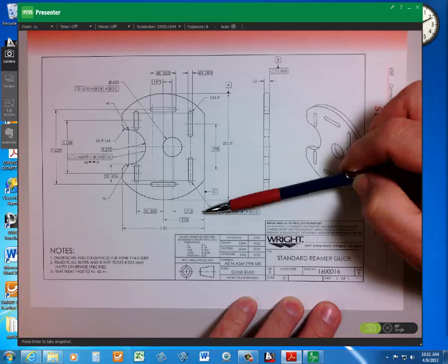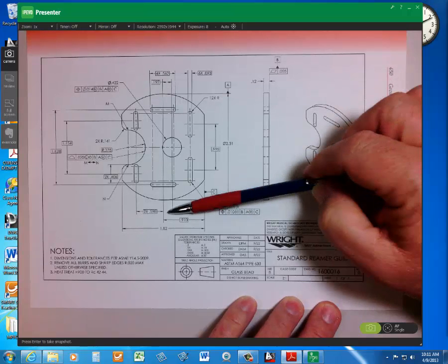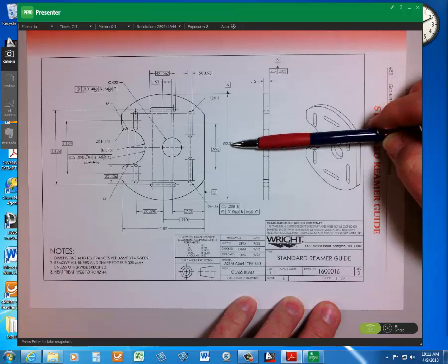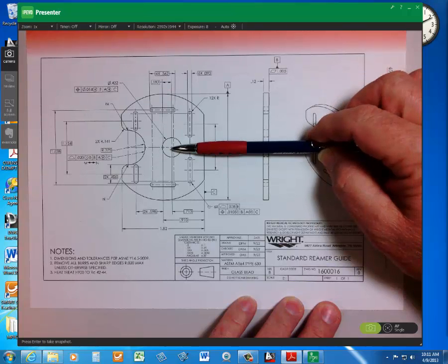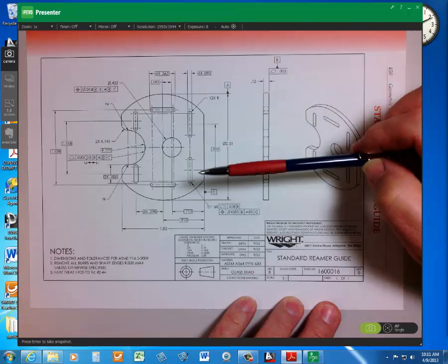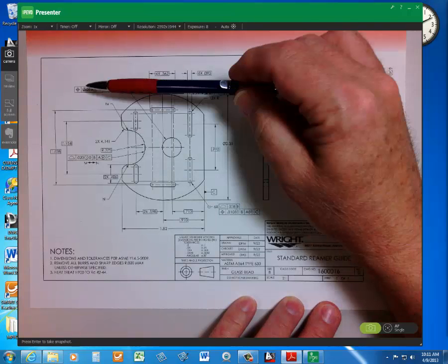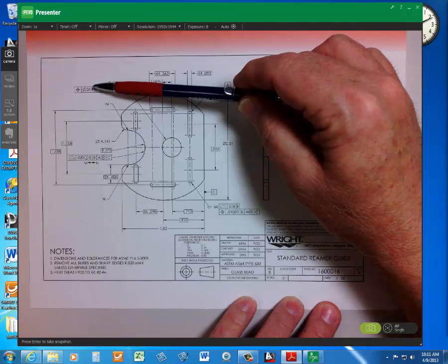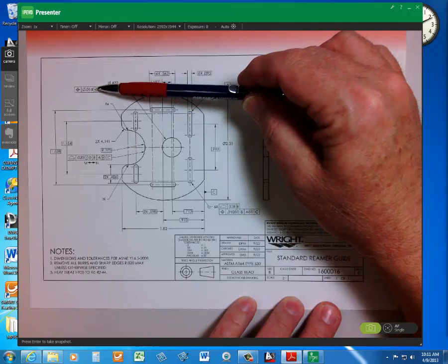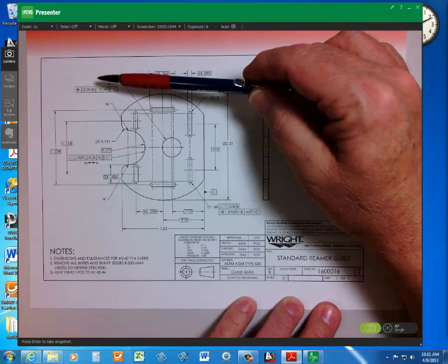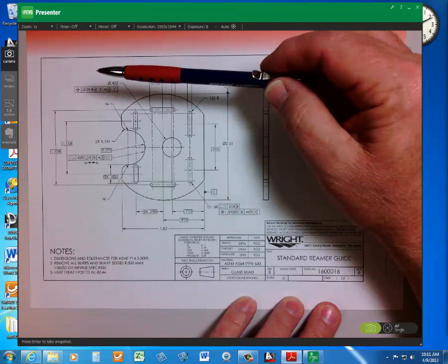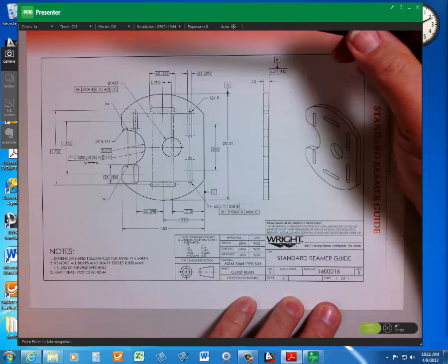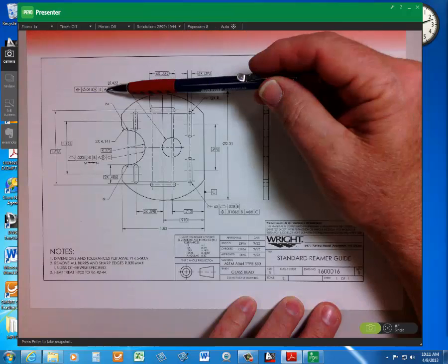Okay, so an exact theoretical perfect measurement this way, and then regardless of feature size, center plane, whatever it's manufactured to, center plane here. The meaning of the information in the feature control frame: it must be a true position within a 14 thousandths diameter tolerance zone or cylindrical zone. Max material condition applies with respect to B, A at max material condition.